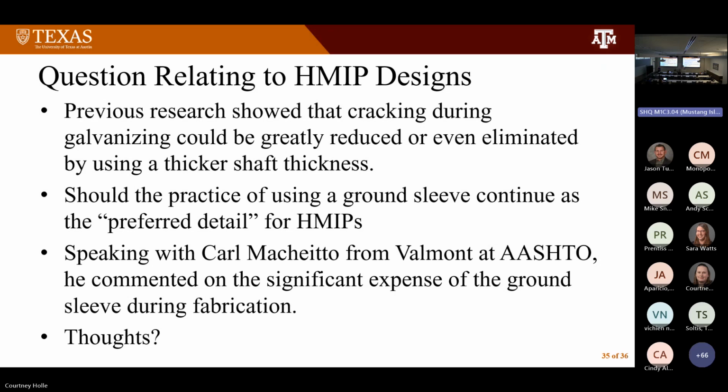No, you're exactly right. When I was calling out tension or compression, I was just explaining why you might see more cracking back in this region, that the gravity is causing that. And it's not the gravity itself, it's fatigue, because of stress cycles. It's going to come mainly from a little bit of a bouncing effect out there that might increase the propensity to crack on the back side of the pole for a CCS. That's the only reason we're trying to note it. There still are some cracks on, we'll call it, the compression side, because it can come from the torsion that's happening and the combined stress state.